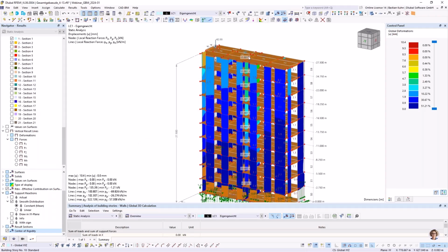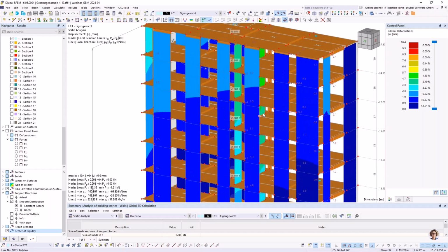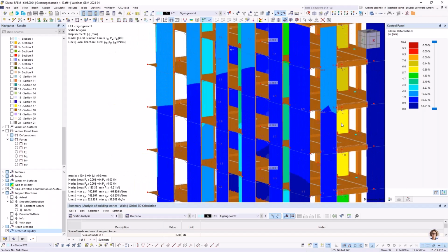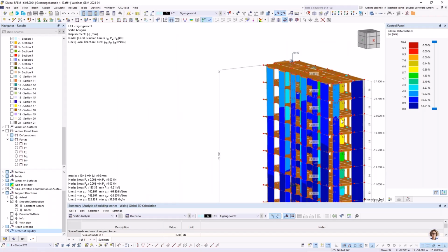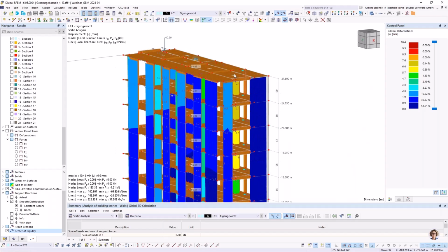So you see the mass center is right here where the staircase is with the concrete, and the stiffness, as this is also a concrete wall and I have a lot of walls in here and also in the center of the building right here on this side. So there are more walls working in horizontal direction on this side, my stiffness center is moved to this point.